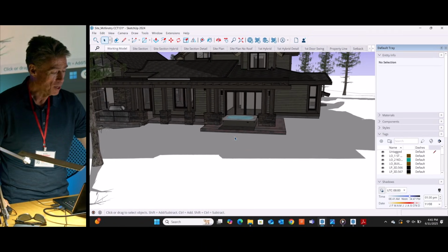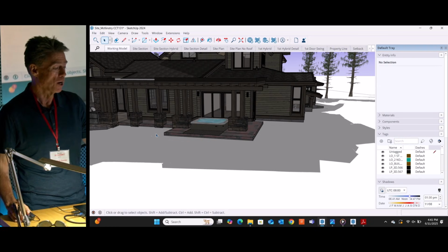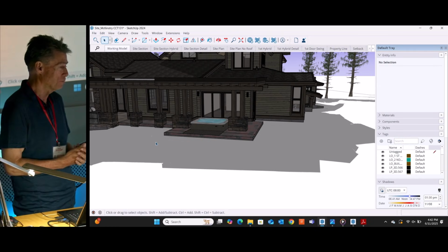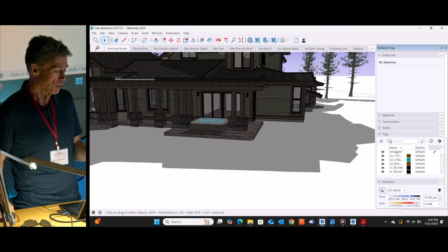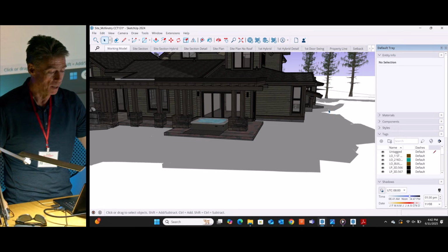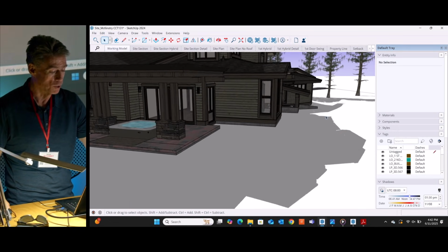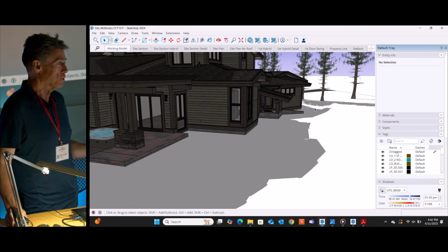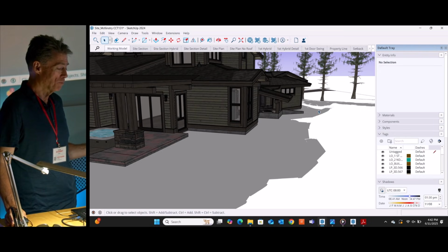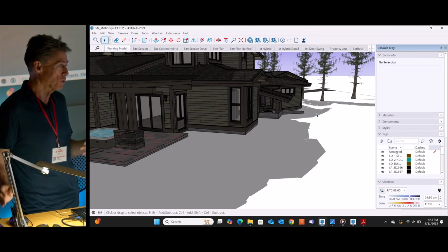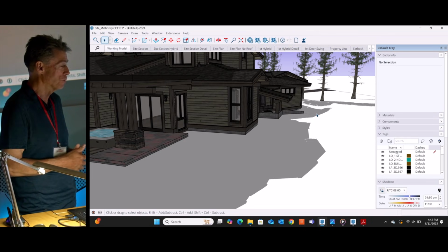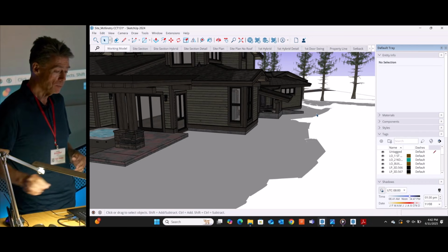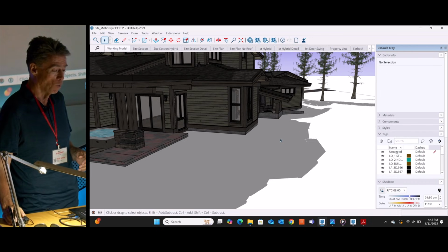I always have to make sure that it's shedding away. So everything from the building out is sloping at that 5% for 10 feet, less if I'm too close to the setback line, as well as the swales. So the swales back here are all maintained. Where you get steeper than 5% for 10 feet, you also then have to maintain a 2% pitch on the swale all the way to its endpoint. And that's all taken care of all the way across the back.